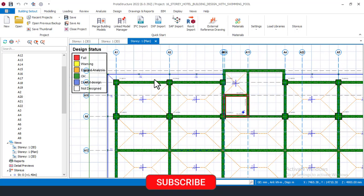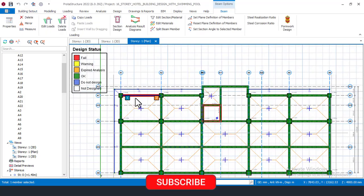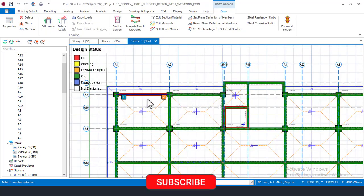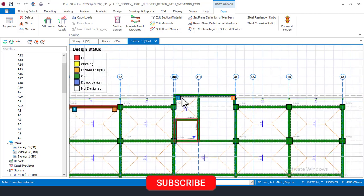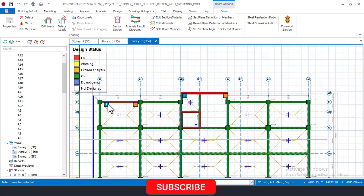When you're doing your beam interactive design, even if your beam is showing green or red or anything, you must check the beam to see the kind of section that was used. It's very important for you to check the beams. So come here, then click on this beam. If I check this beam now, I have checked all the beams on this line, which is these two beams here. So I can choose to start from here, so that I will not miss any at all. I will start and deal with all the horizontal beams first, and then the vertical ones.